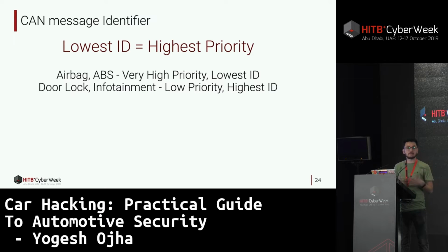If there are two packets coming at the same time, it needs to have arbitration. Suppose there are two nodes sending messages at the very same time, the message with the dominant ID, or the highest priority, will override the one with the lowest priority.